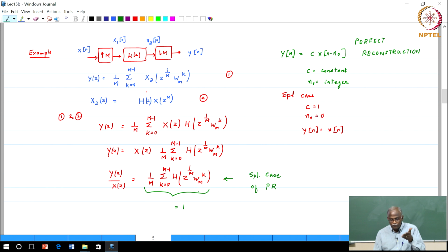Okay. So, if you downsample h of n, which polyphase component have you picked up in this case? If you sent in h of n and you downsampled by a factor of m, what you would get here is h of mn.